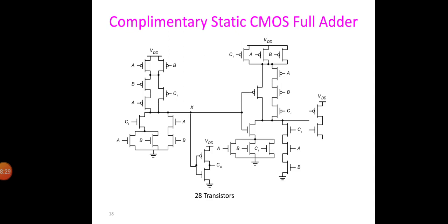One reason is that tall PMOS transistor stacks are present in both carry and sum generation circuits. And the intrinsic load capacitance of the Co' signal is large and consists of 2 diffusion and 6 gate capacitances plus the wiring capacitance. The signal propagates through 2 inverting stages in the carry generation circuit, and as mentioned earlier, minimizing the carry path delay is the prime goal of the designer to speed up the adder circuits. Given the small load at the output of the carry chain, having 2 logic stages is too high a number and leads to extra delay. The sum generation requires 1 extra logic stage, but that is not that important, since this factor appears only once in the propagation delay of the ripple carry adder.